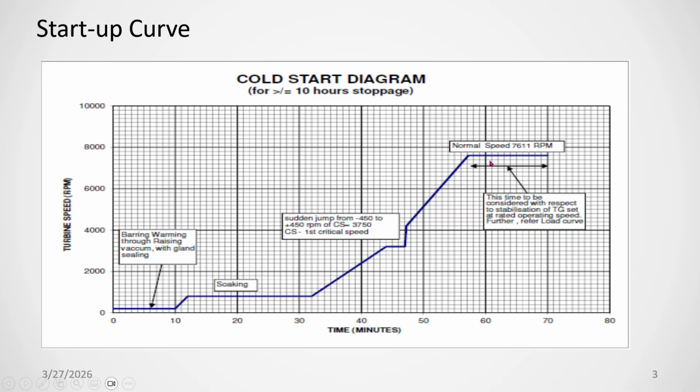not, etc. Keep the turbine running at that temperature and at that RPM for at least 15 minutes, to check all the parameters, the turbine governing system function, all the expansion, etc. And then you can load the turbine, maybe with the generator, maybe with the process gas compressor, etc. So this is the cold startup.